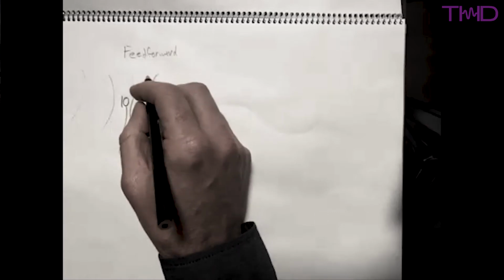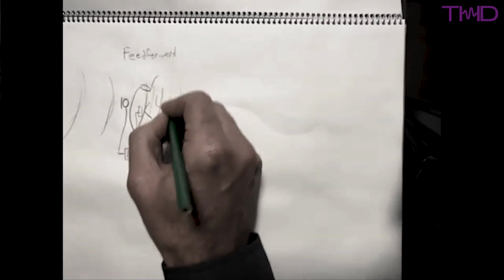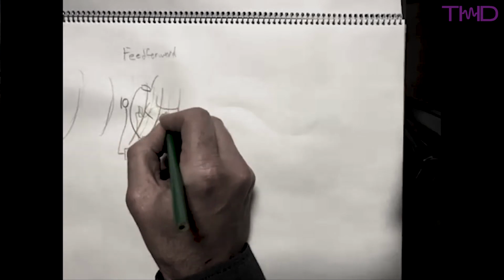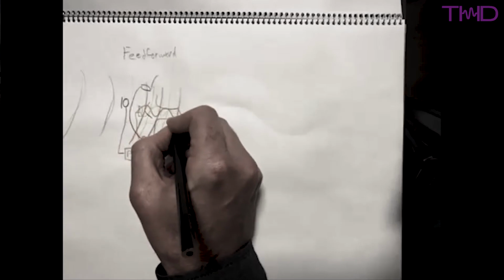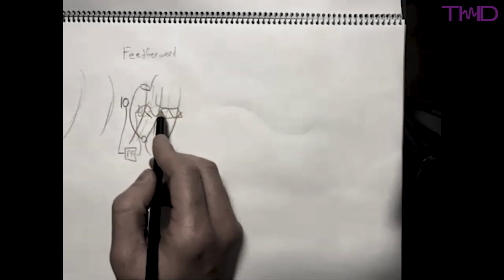I've got colored pencils, so we'll do that. Imagine those are the positive wave fronts of that outside noise. If you get your speaker positive wave fronts to end up exactly halfway, this would be a down and an up and a down and an up, and this would be an up and a down and an up and a down. They would cancel each other out. And in the ideal sense, there's no connection: the sound from the speaker never reaches that feed-forward microphone, so you would never have the stability problem.